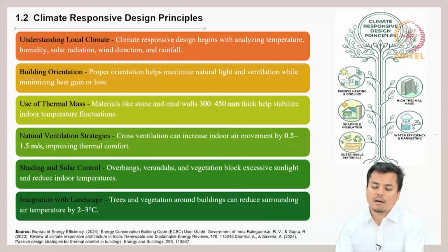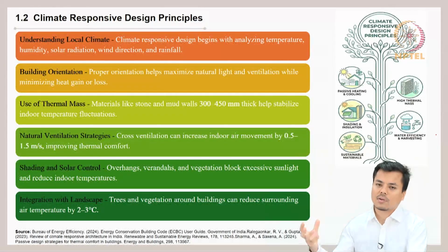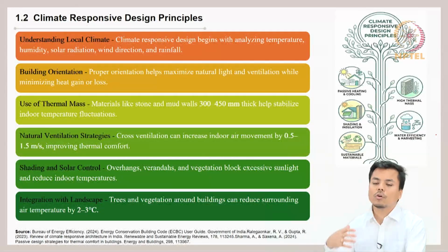Then next is the building orientation. If your building is oriented properly, and you are designing in a cold and cloudy climatic region or a cold and sunny climatic region, your attempt should be to maximize the heat gain in that region, contrary to the buildings that you will design in a hot and dry climatic region or in a warm and humid climatic region.